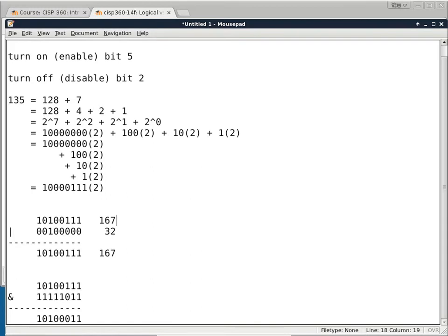It does not change the value, because it's turning a 0 into a 1, but if it was a 1 already, it doesn't do a single thing. So that's why I did not want to use an addition. I want to use a bitwise OR, so that the other bits do not get changed.